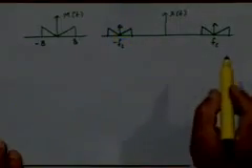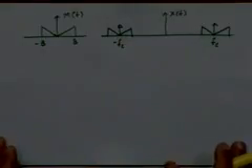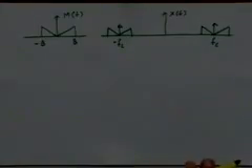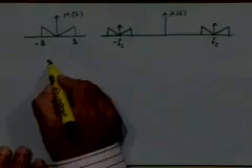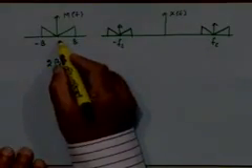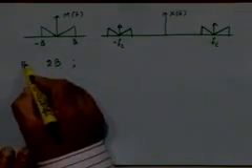In this case we have a localized specific value of the carrier component along with the modulated signal, right? So the spectral properties of this signal are to some extent similar to that of the DSB-SC, in the sense that the bandwidth required is 2B as against the message bandwidth of B.